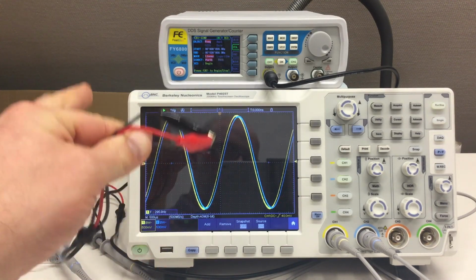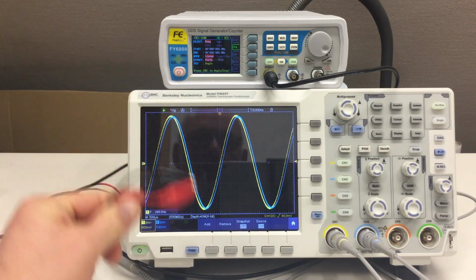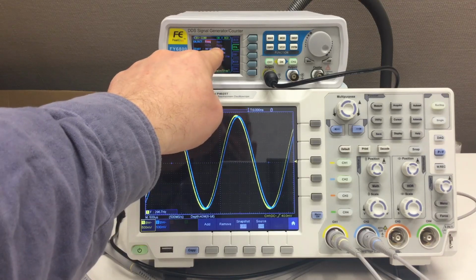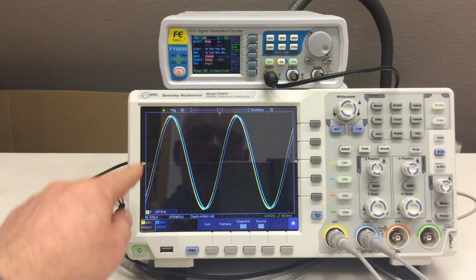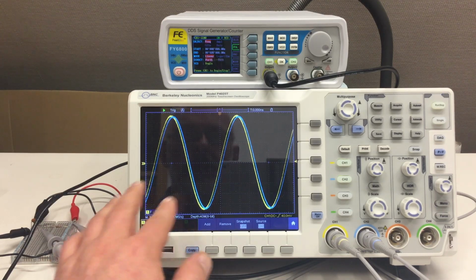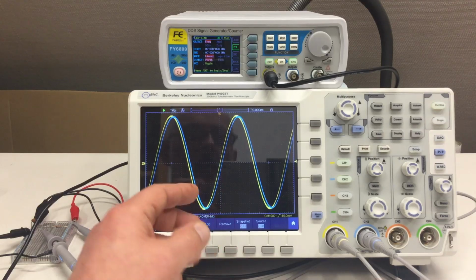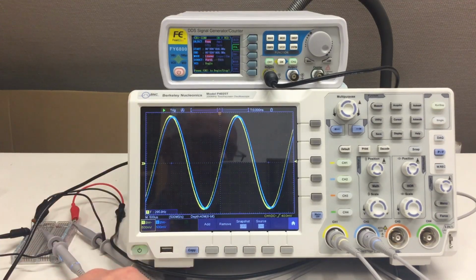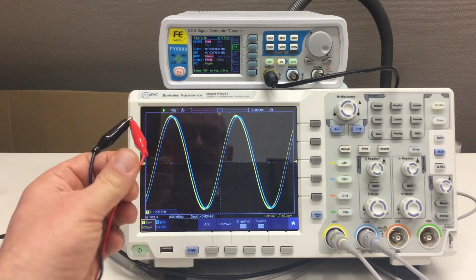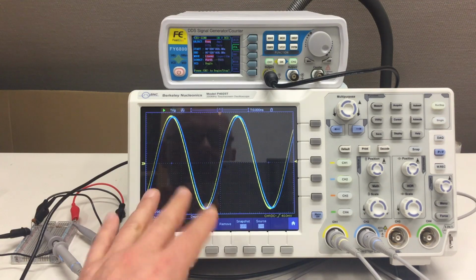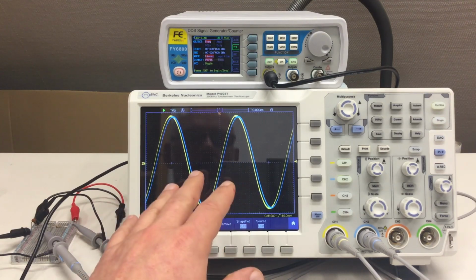I still have shorted the VCO input of the function generator, and I changed the start frequency to 20 hertz. And I'm getting out 290, 300 hertz. So right off the bat, we obviously have here an undesirable offset of the frequency of about something between 250 and 300 Hertz.